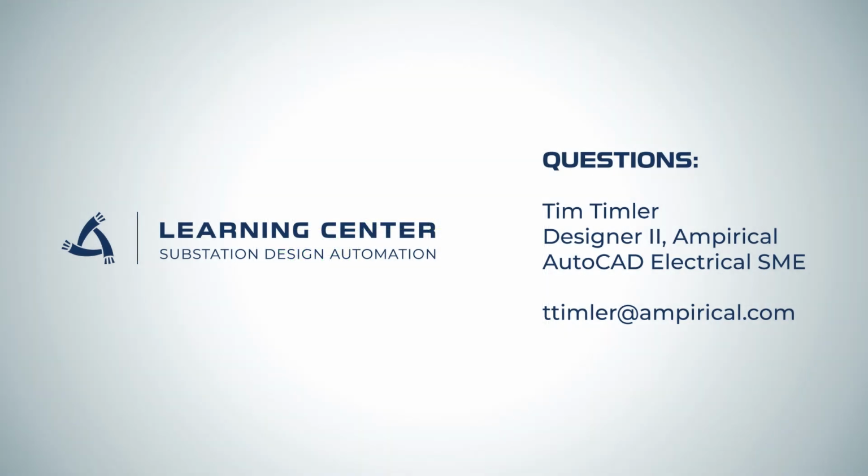This demonstration was an example of creating a fairly complex schematic symbol and then connecting it to the icon menu. As you can see, there's a lot to consider when building a good schematic symbol. It takes time to clean up the geometry and consider attribute placement. It's also worth considering whether a complex symbol you're wanting to create can be broken up into a parent-child relationship to give it more flexibility. Sometimes it's prudent, sometimes it's not.